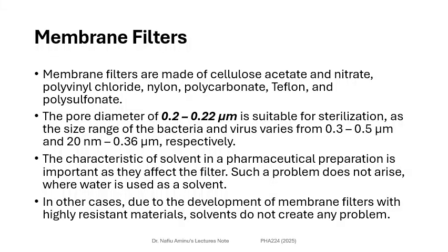The characteristics of solvents in pharmaceutical preparations are important as they affect the filter. Such a problem does not arise where water is used as a medium. Yeah, because we have different ingredients or raw materials that can be present in different types of solvents. So we have to make sure we choose the right filter medium for a particular solvent. In other cases, due to the development of membrane filters with highly resistant material, solvents do not create any problem, for some other types of filters.